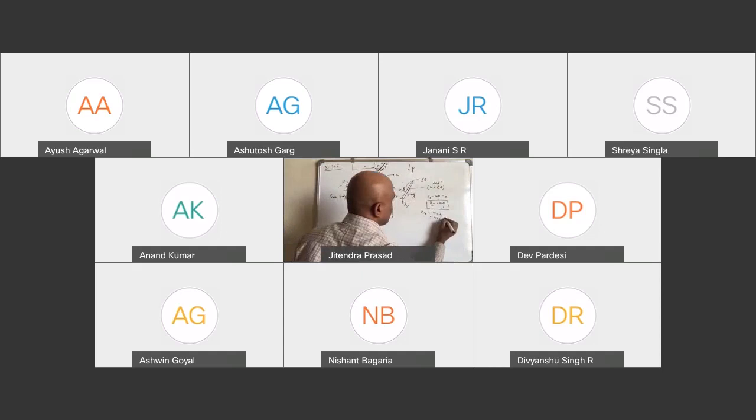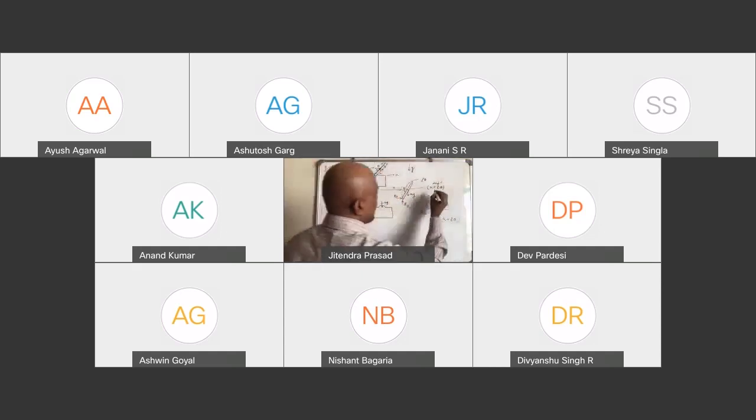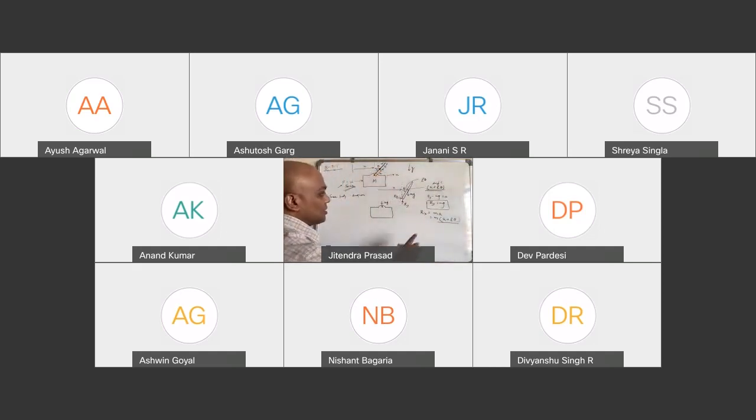What you get is x double dot plus L theta double dot. Why? Because this is the displacement, and hence the total force Rx has to be equal to m a, where a is equal to x double dot plus L theta double dot. L is a constant, right? So hence you have this equation, and you get the value of Rx as well.